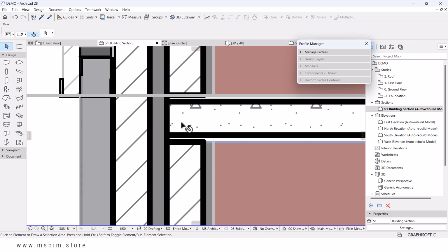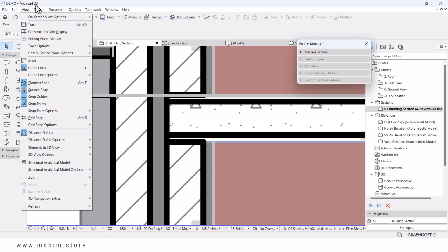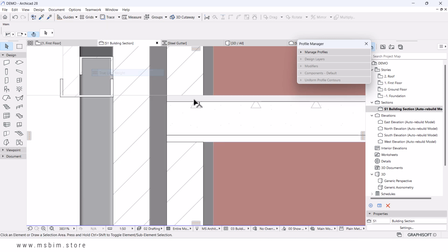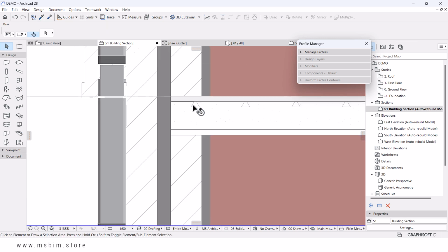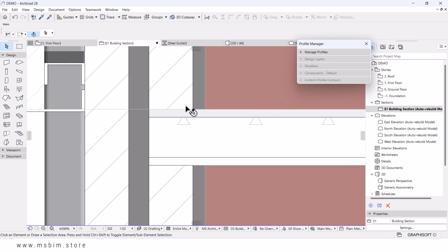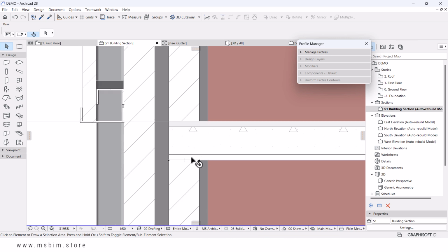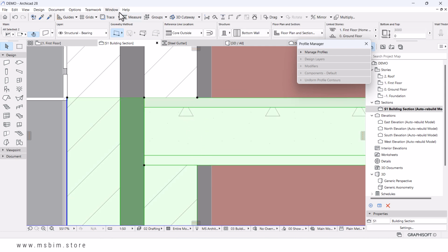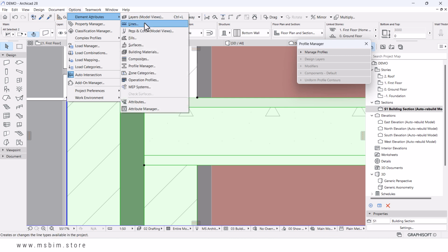And then one thing that we need to be very careful with, let me come here and switch off the line weights, the true line weights. You see, we can't have a floor finish going through all the way. It has to stop on the core brick, as well as the underneath soffit for our slab. So we need to select this material and adjust its intersection priority.